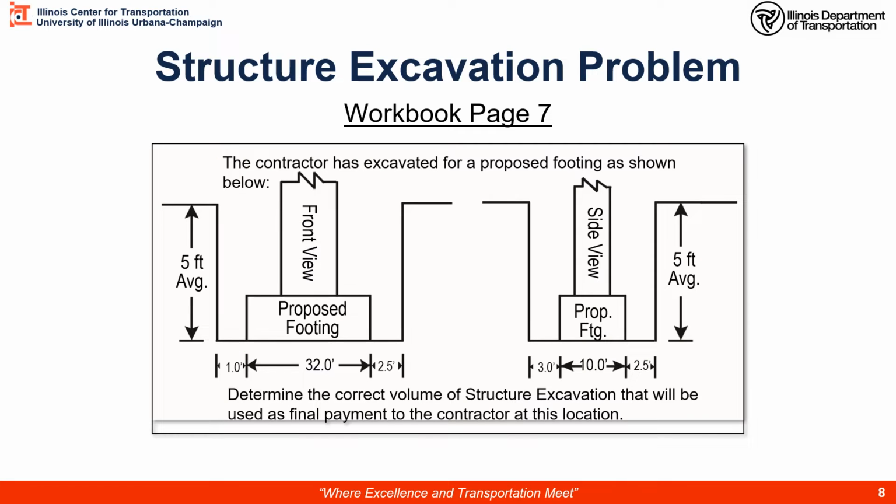Let's go to workbook page 7 and perform this problem. Just a few hints. Remember what our spec requirement is on paying up to 2 feet beyond the footing. Let's see what we have going on here. So with that hint, perform your calculations for the cubic yards of structure excavation.